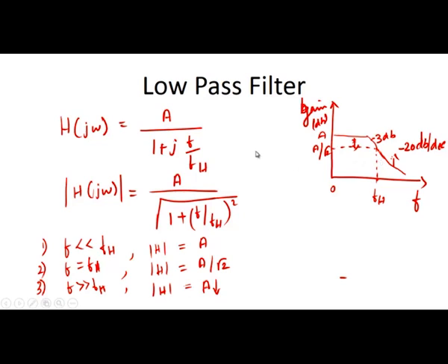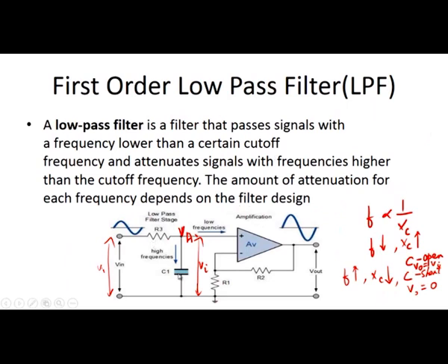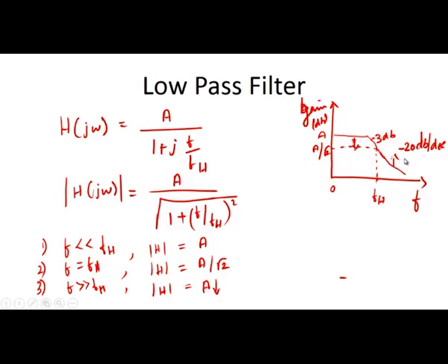For example, if we go for a second order filter, in the circuit we have two sets of this R and C combination in this same setup. So, if we have two sets of R and C combination, then in the frequency response another minus 20 dB per decade roll off rate will add up. So, totally minus 40 dB per decade.